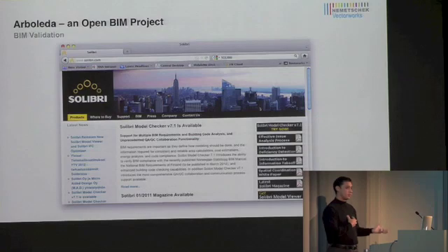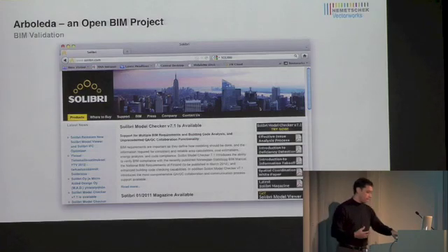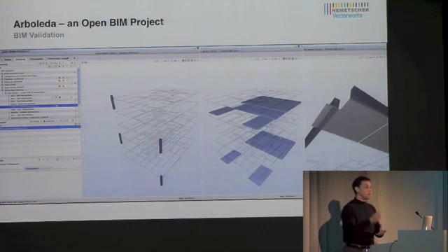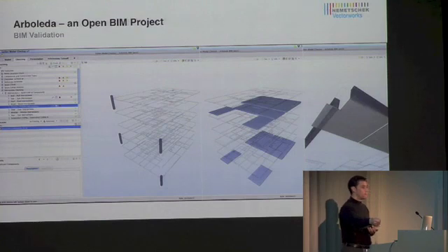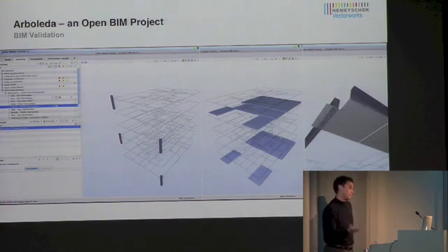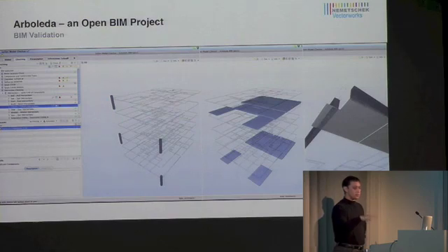Now, I had access to Solibri Model Checker, and this one will help me to validate and test my model before I send it out. Not just, hey, here's my IFC, contractor, there you go. You have to test it, you have to validate it, bring down the mistakes. And I had mistakes. Columns were repeated. Visually inside Vectorworks, I thought everything was just fine, but once you bring it into this kind of software, you realize that